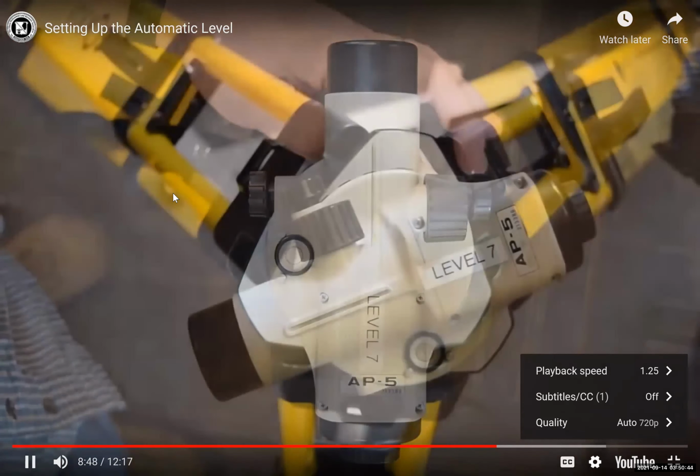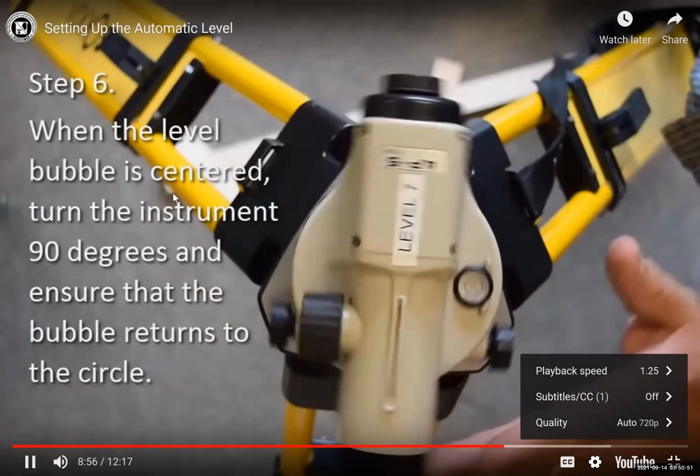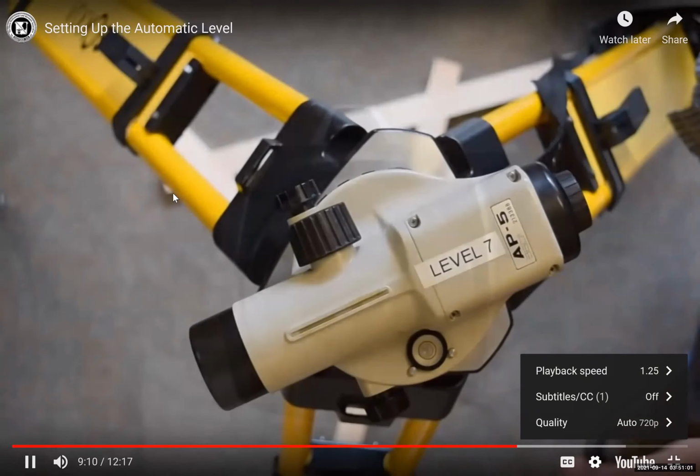When the bubble is centered, turn the instrument roughly 90 degrees and ensure that the bubble returns to the circle. If it doesn't, adjust the screws and recheck it. If upon rechecking it, it's still not centered, well, then the instrument may require maintenance.